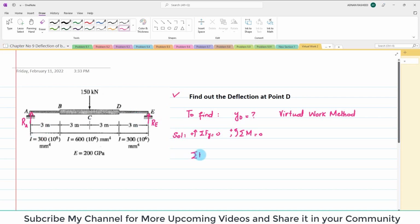So I will apply the sum of all moments about point E equal to 0, taking counterclockwise as positive. You can see at point E there are two forces which will produce moment about point E. One is this 150 kilonewton, and another is the reaction force RA. RA into the perpendicular distance, which is the total distance of 12. So RA into 12, and it will produce a clockwise moment, so it will be negative. The second force producing moment about point E is 150 kilonewton, so 150 into the perpendicular distance of 6, and it will be positive because it produces a counterclockwise moment. So 150 kilonewton into 6 minus RA into 12 equals 0. From here we get RA equal to 75 kilonewton.